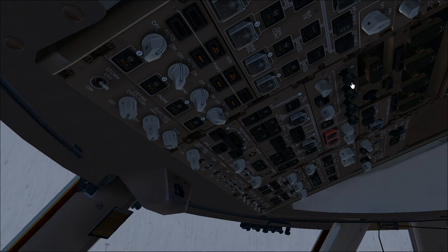You can start up 2 engines per time. In case you need just to start 1 engine per time, you can just set up 1 pack off usually. But mainly they actually turn off 2 packs. In the case the temperature is very high, probably you need to turn off all the 3 packs to do a dual engine start at the same time.